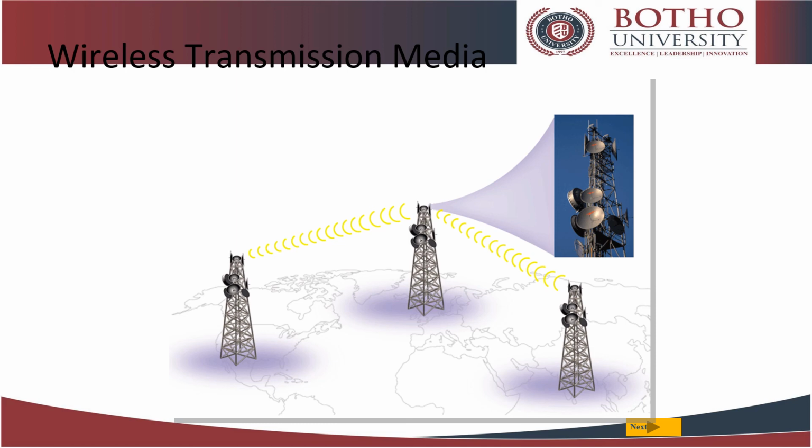A microwave link is a communication system that uses a beam of radio waves in the microwave frequency range to transmit video, audio, or data between two locations, which can be from just a few feet or meters to several miles or kilometers apart. Microwaves are electromagnetic waves with frequencies between 300 MHz and 300 GHz in the electromagnetic spectrum, while radio waves are electromagnetic waves within the frequencies of 30 kHz to 300 GHz and include microwaves.